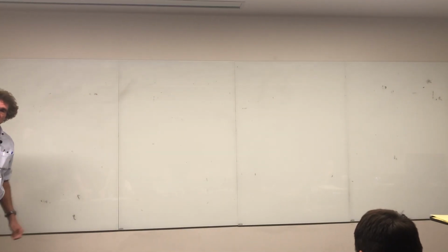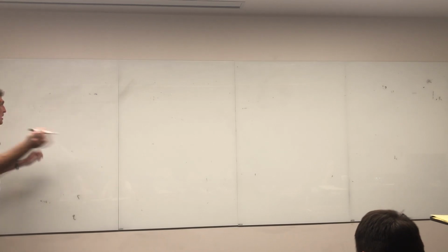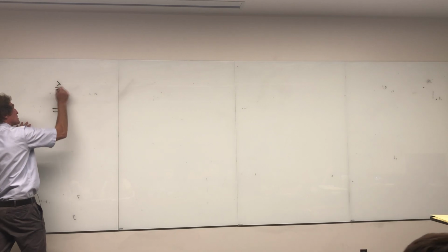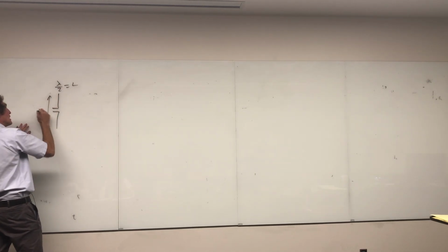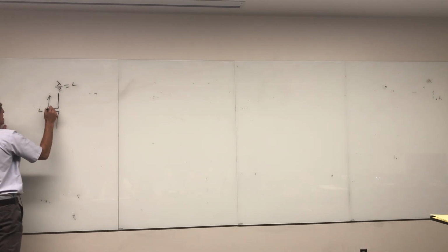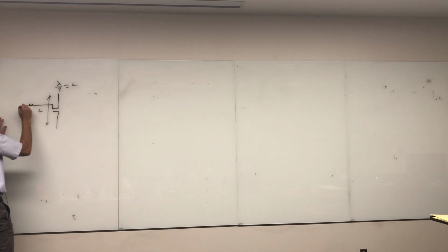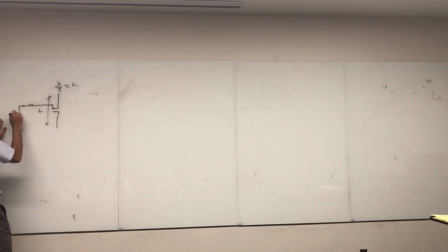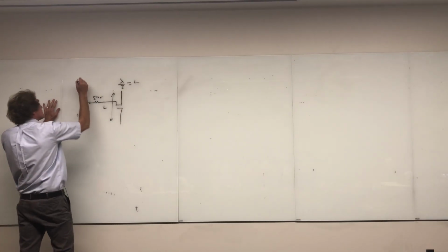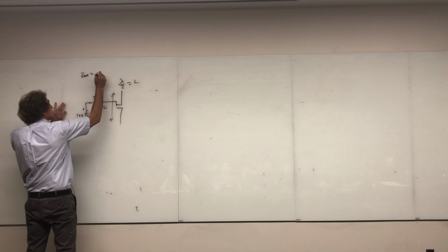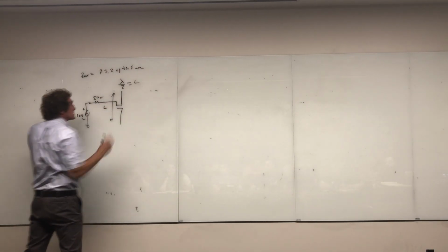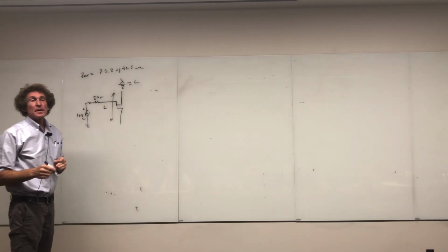It's sequentially the next one after that. What is it? A lossless half-wave dipole. All right, hold on. So now the actual dipole is lambda over 2 in length. Lossless is important. It's driven by a 10-volt, 50 ohm source. So there's a source here, plus to minus 10 volts, with 50 ohms here. The antenna itself, Z antenna, has 73.2 plus j42.5 ohms. Remember this, all right? Now that's a half-wave dipole, but keep going.